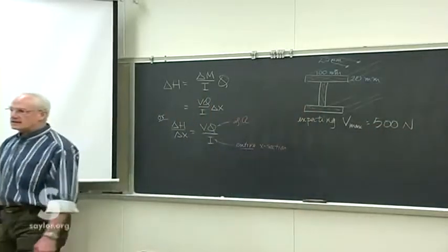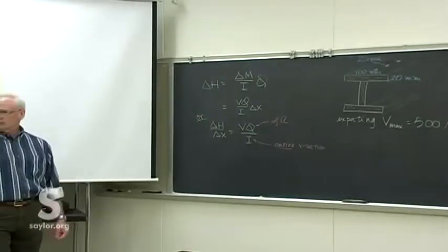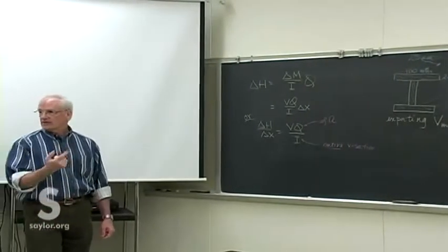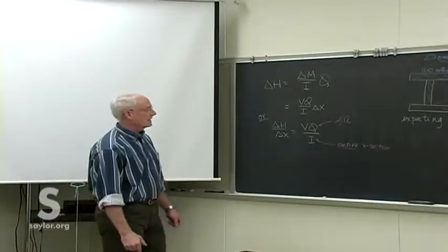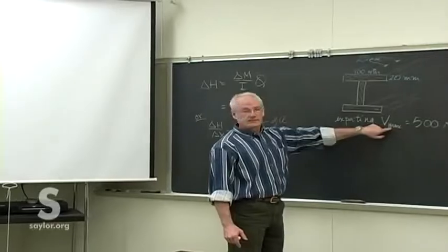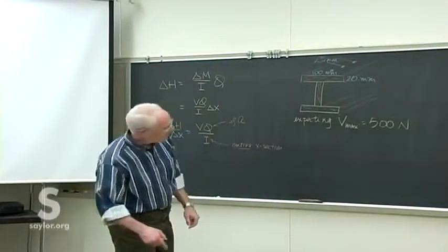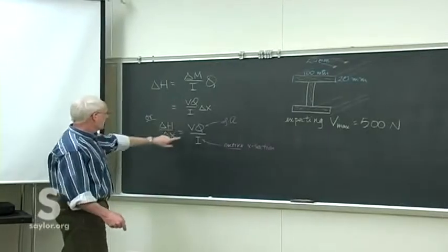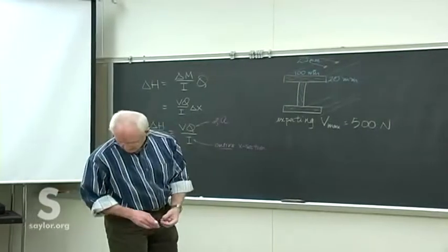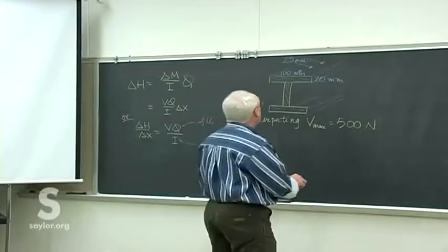We would find that just like we would have found it last fall. We look at the beam and see how it's loaded, figure out what the reactions are, and then figure out what the shear moment diagrams look like. See what the maximum shear is, and then build the beam to resist that maximum shear. Because we've seen now that it determines what the cross-sectional area is.